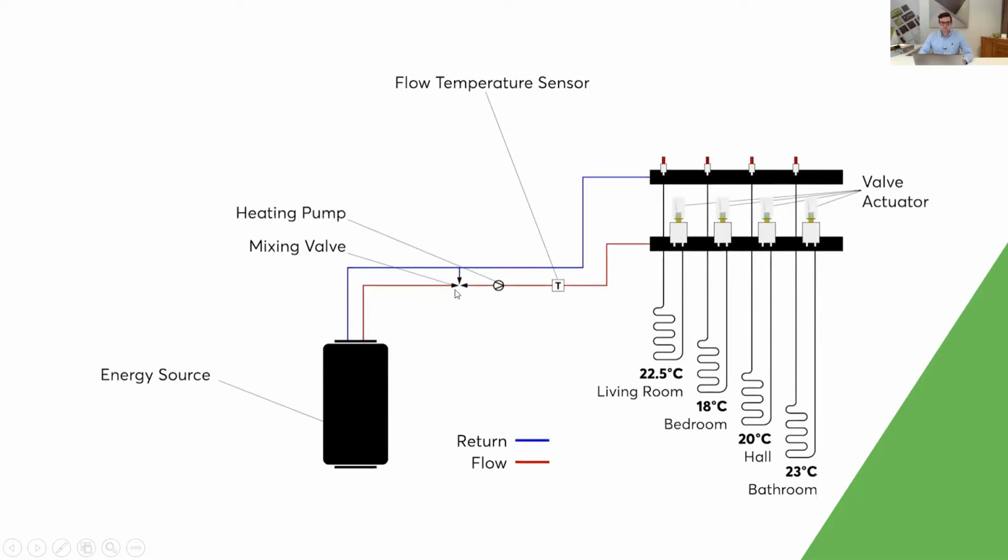We're then going to have a mixing valve. Mixing valve we would typically call a blending valve. So when you buy a manifold set, it usually comes with a pump and a blending valve, and it's normally a manual twisty blending valve. Now you can get electronic blending valves, and what we can do then is actually measure the flow temperature, and the room controllers can tell us how much temperature they actually need to heat the room up and maintain that heat.